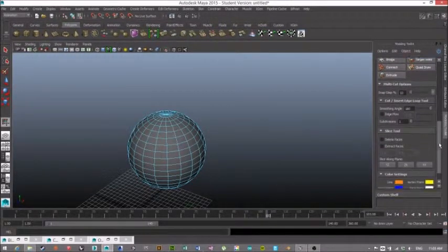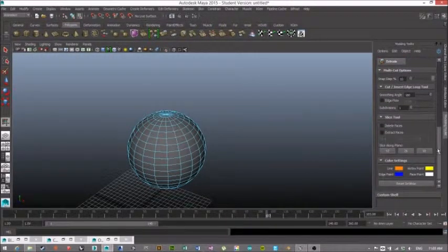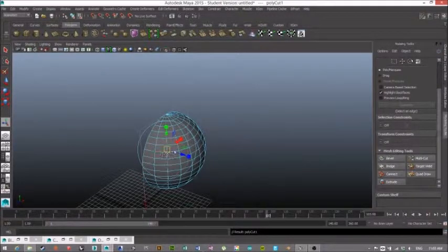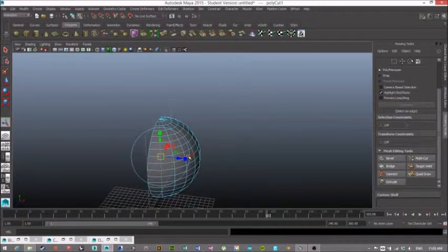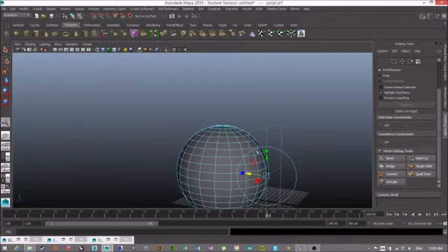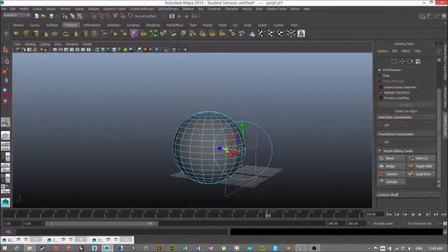What we are going to do is we scroll down and we're just going to click delete faces. And we'll do it in the YZ plane. And instantly, it's cut. Now once again, this cut happens where the pivot point is, so you can change where the pivot point is if you want it to cut in different places. But you can see how easy that is. Let's just rotate over. Great, so you're cutting the geometry.